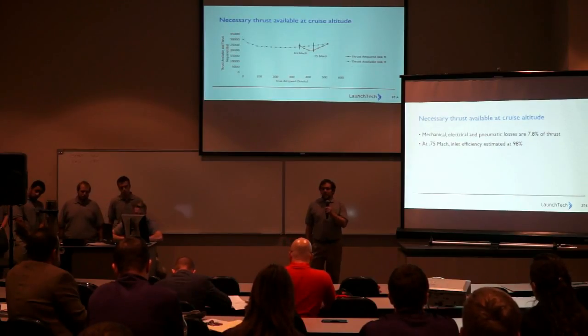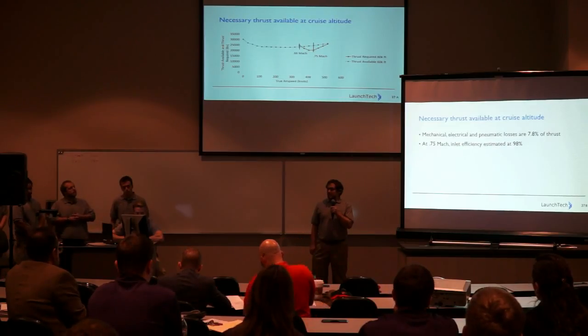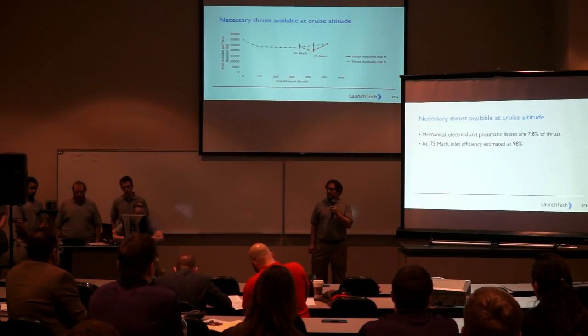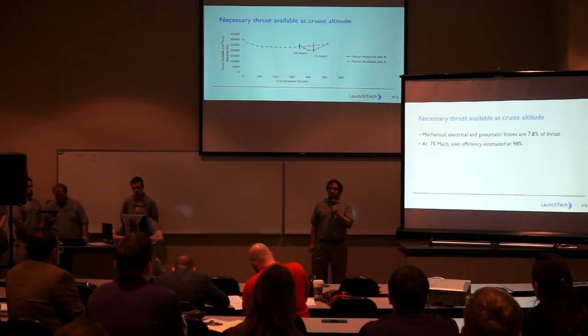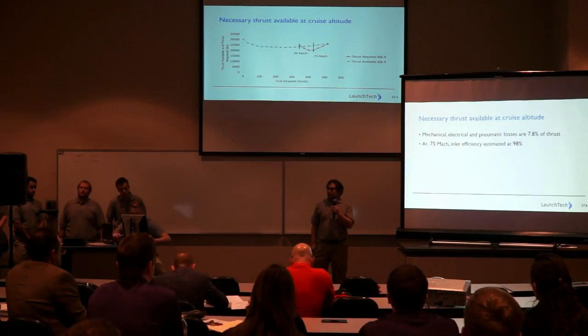And shown on the primary slide is the thrust available versus thrust required for 60,000 feet. At this altitude, the PT-1 is planned to fly at 0.75 Mach, and it's capable of flying between 0.66 Mach and 0.9 Mach, chosen as the max speed, as the engines are unlikely to perform past this speed.